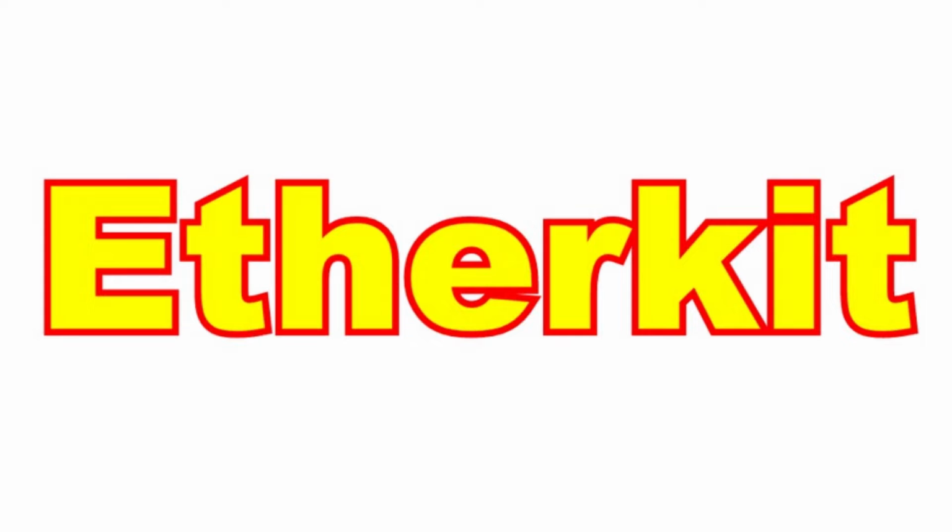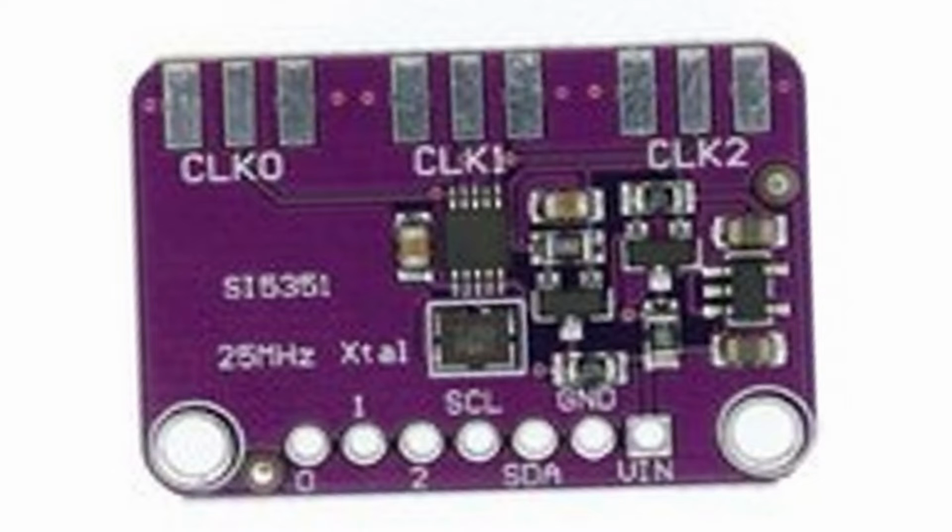The si5351 operates on the I2C bus, so it is a perfect device for learning more about I2C on the Raspberry Pi Pico. There is a handy library available for the si5351 that we will be using called EtherKit. The library uses the Wire function to communicate with the si5351, and it cannot be changed to Wire1 without modifying the library. So this time we will be using Wire instead of Wire1, which we used for the display in the previous video.